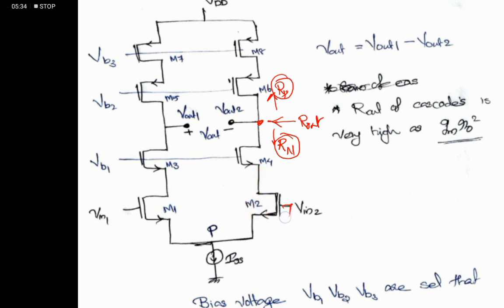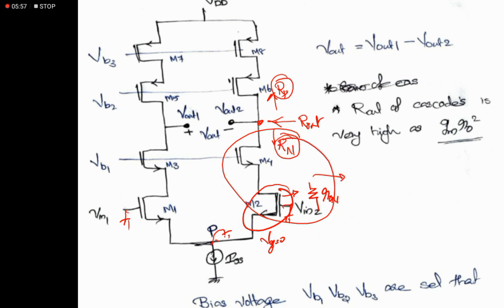For evaluating resistance we need to ground all the inputs, and this is also a virtual ground, so the value of VGS is 0 here. Due to that there is no input signal, and we can simply replace it with its internal resistance R0N. So this becomes a MOSFET with some bias VB and the degenerative resistance R0N.